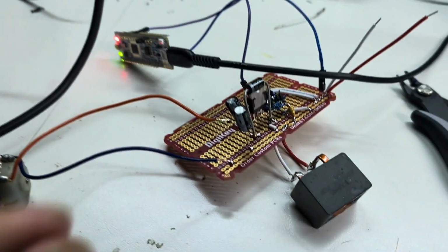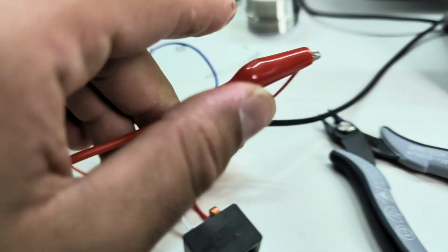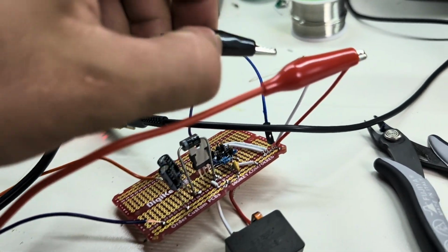Okay, so when we put on the power supply, the motor did like a peak of 300 milliamp. So the components on this circuit should hold 300 milliamp. So I'm not expecting anything to explode or anything. So we're gonna try it one more time. I've removed the resistor. If the motor doesn't spin, I'll be very confused, to be honest.